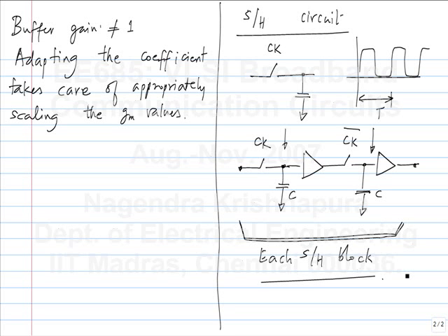This is sampled at the level, right? But when the switch turns off is the sampling instant. So you have something like this. If you have this waveform going to the switch, it will follow it for some time and do this thing, right? So basically the value that is stored is the value at the instant at which the switch opens. So it is transparent for half a clock cycle, but the sampled value is when the switch opens.